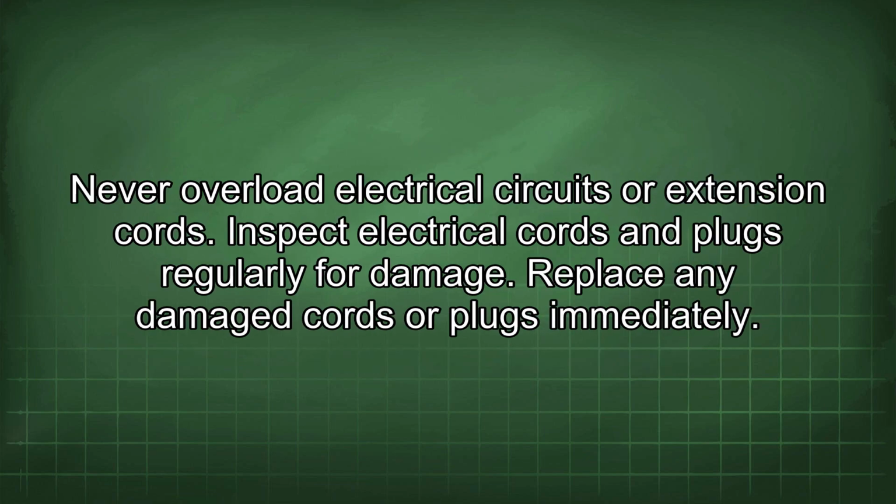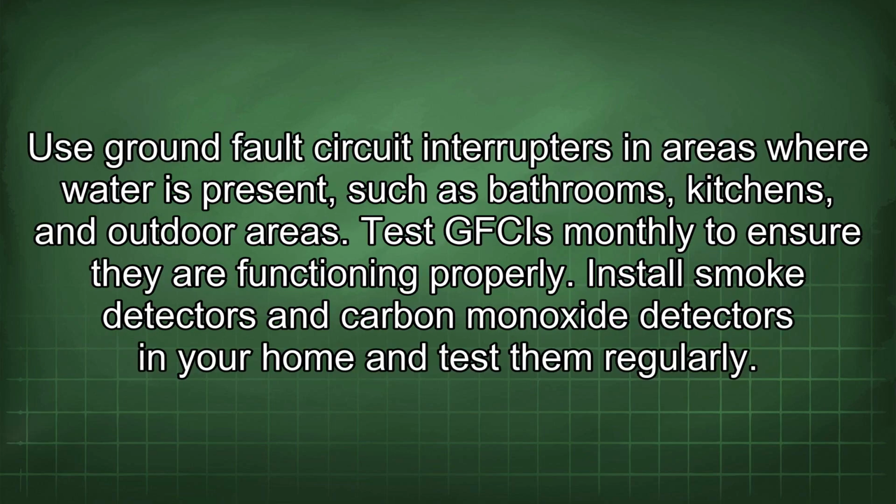Never overload electrical circuits or extension cords. Inspect electrical cords and plugs regularly for damage. Replace any damaged cords or plugs immediately. Use ground fault circuit interrupters in areas where water is present, such as bathrooms, kitchens, and outdoor areas. Test GFCIs monthly to ensure they are functioning properly.